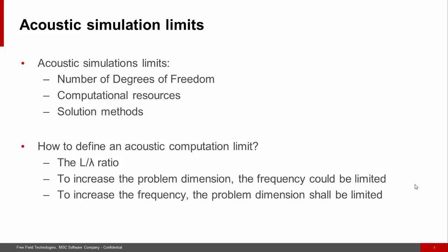If you use Actran Acoustics, for example, which is a standard FEM solver, most likely your computational resources available will allow you to solve problems up to around an L over lambda ratio of less than 50 within a reasonable time from an industrial perspective with the current computational technologies.